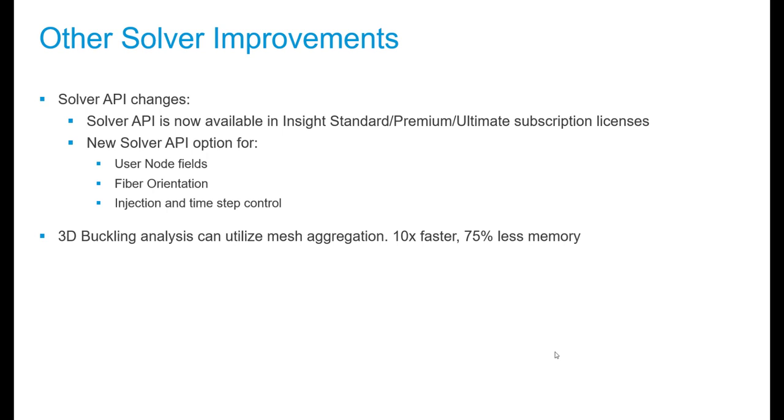It's still a very large analysis, so we're not going to be switching it on for every small deflection analysis, because the buckling analysis would still take longer than the small deflection analysis. So it would not make sense to have an automatic setting like we have in the midplane world, where we run a buckling analysis first, and then depending on the results, go for either a large deflection or a small deflection. The buckling analysis will still run for a long time, so it is not practical in that sense, but it is still a lot faster and more viable to run than before. So that's good.